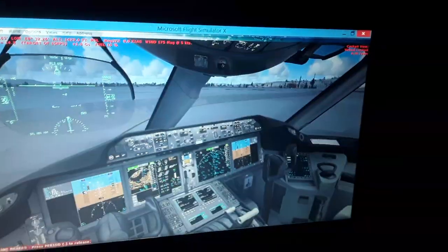also the overhead panel. We'll show you how to start up the engines, also how to use all the autopilot flight director system panel, the thrust levers, the flight controls. So we have also in the primary flight display the flight director crossbars for manual guidance of the aircraft, the autopilot crossbars for automatic guidance of the aircraft, the angle of attack of the aircraft as it flies in the flight mode annunciation with the autopilot and the autothrottle.